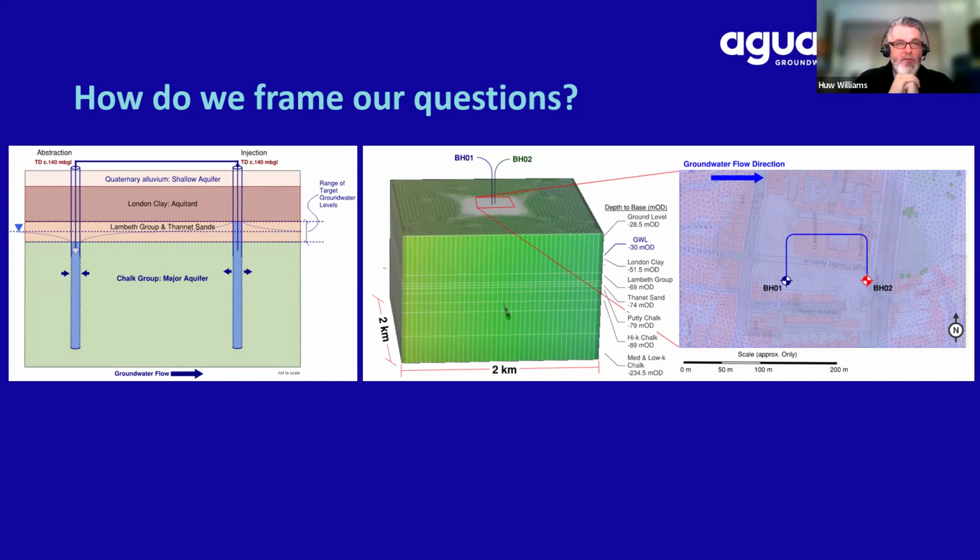So we have this geological layering. We put that into FEFLOW, which is the green block in the middle. We use a block model scenario normally because we don't want to have to model the entire Cretaceous chalk aquifer. That would be unrealistic. So we simplify that to a local block model, whereby our main interest is to replicate the groundwater conditions, the geological conditions, only in the vicinity of the site, because the argument being that we're only going to have a fairly small groundwater and temperature perturbation within the aquifer locally.